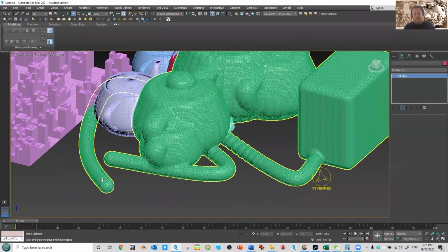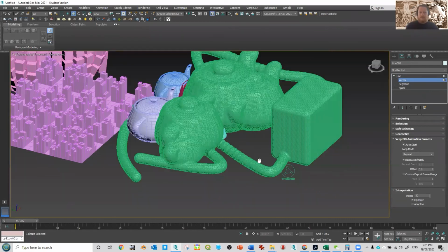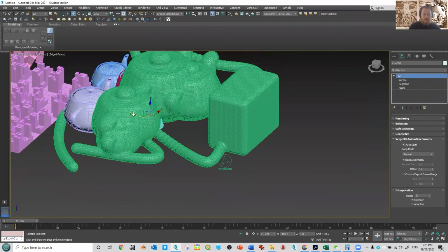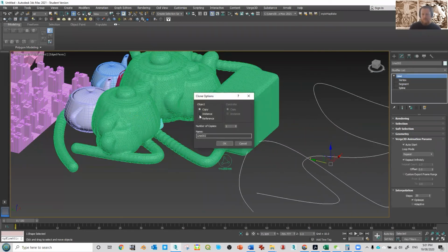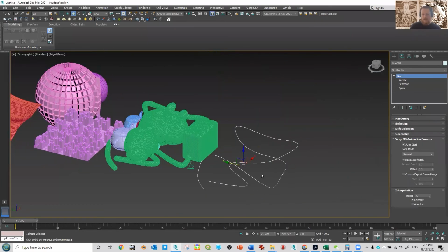And again, very nicely, you can edit the original spline. So if I go into the sub object, actually, it's a bit hard to see what's going on. What I might do is let's try this. I'll shift and move as an instance. So now I've got a copy of that spline, but over here I can see what I'm doing.